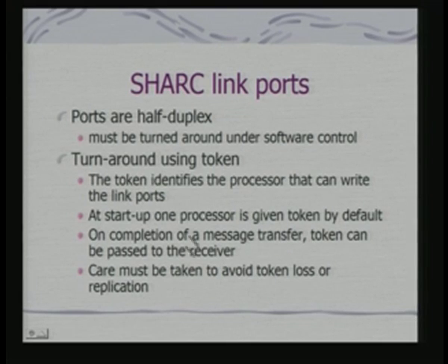At startup, one processor is given the token by default. On completion of a message transfer, which may involve a sequence of 8 bytes, the token can be passed to the receiver. When the token is received, the receiver will change mode and become a transmitter. That's how the turnaround can be done using the token.